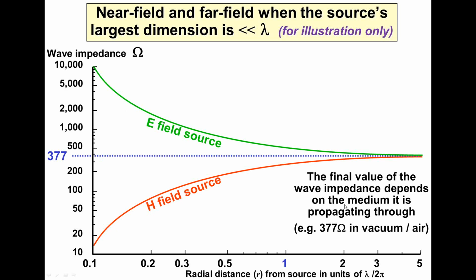If they were traveling in oil, say we're interested in some big oil tank for some reason, then that impedance would probably be more like about 150 ohms, 180 ohms, because of the dielectric constant of the oil being about 3.